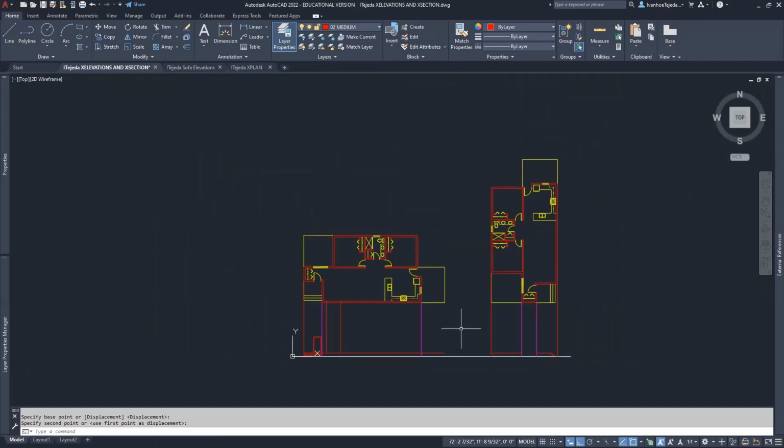Now, you still don't know what type of roof you might be using, so now's a good time to think about that. Consider what kind of heights you want in your ceilings inside, and then calculate where you would like your roof to begin. Usually, just to keep things relatively simple and straightforward here for us, rule of thumb, inside your spaces, you want your ceilings to be at least 8 feet high. They can always go higher. And then just assume that you're going to have 1 foot for your structure there. So if you have a flat roof, it's going to be at least 1 foot that you need. I'm just looking to see you begin these elevations and understand that.